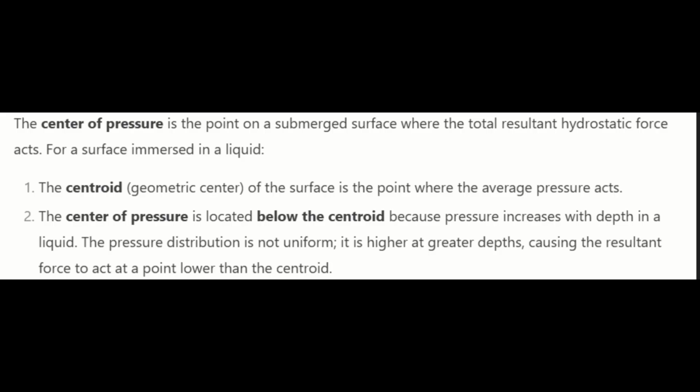So the center of pressure is where the hydrostatic force is acting, right? So the center of pressure would be increasing with the distance. Okay, p is equal to rho g h, and so it would increase with the distance. So it would be maximum at the very lower part.